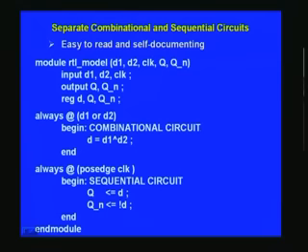It's a good practice to have this. And this does nothing more than take the exclusive OR of two inputs and assign it to D. That is what this logic is doing. This is just the D input for a flip flop, and the flip flop is written in a segregated block here, which is also an always block, with the action taken at the positive edge of the clock. For simplicity, I have omitted the negative edge of reset, which we considered earlier.